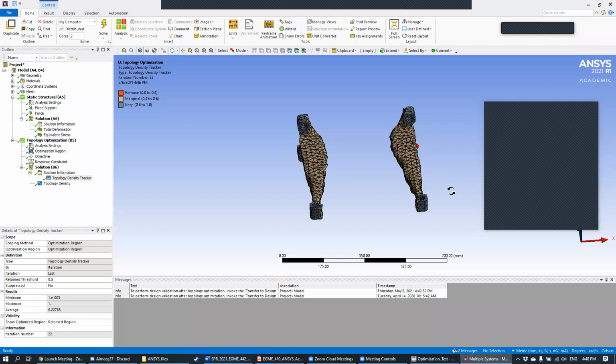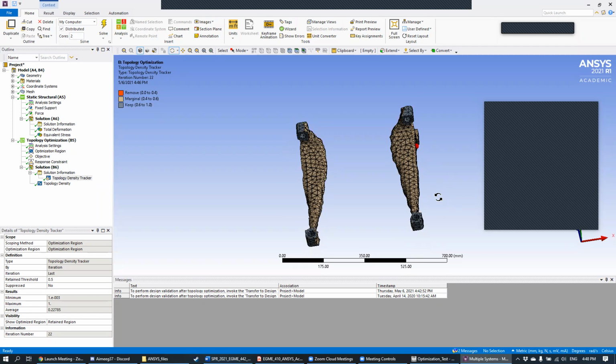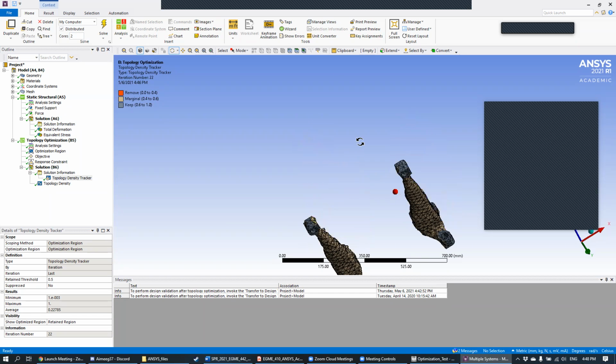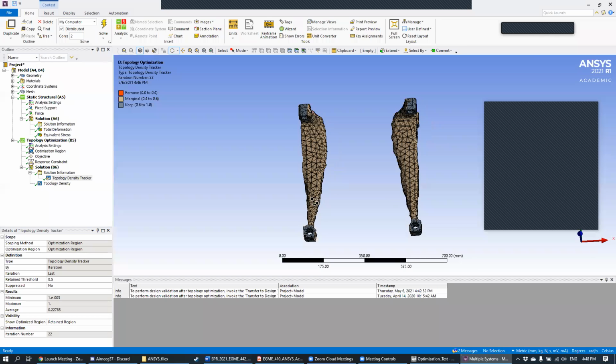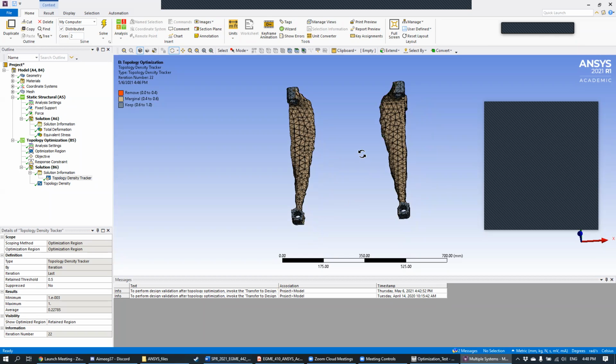Remember, optimization doesn't find the perfect solution, but it finds one that's pretty good given the characteristics that you gave it, right? And of course, there are a lot of other factors that come into play when you're designing a part. A big factor is ease of manufacturability. Even though this geometry right here might be optimized in terms of the stress distribution, it's definitely not optimized in terms of being easy to manufacture. So when you use this tool, you have to combine knowledge and factors from a lot of different sources in order to get the perfect geometry for your application.